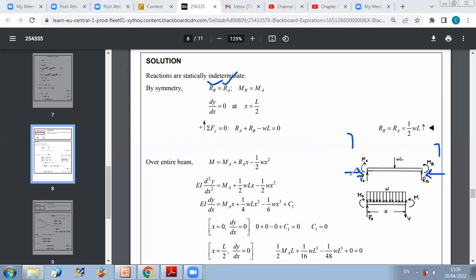And like we have seen before in statics, if you have a thermal effect, you can have expansion of your beam. But here you don't have any data about this. So we can consider that since no X load is applied and there is no source for, let's say, stretching of the beam, then we can say that both the AX and BX reactions are 0.